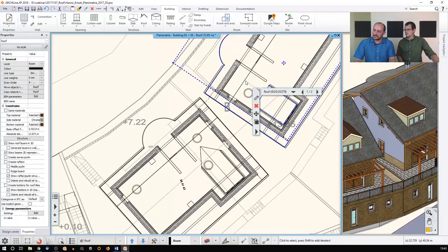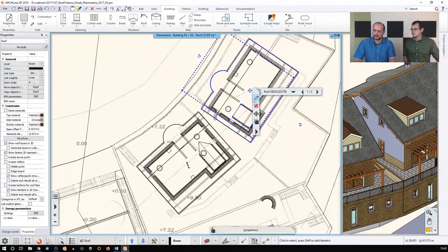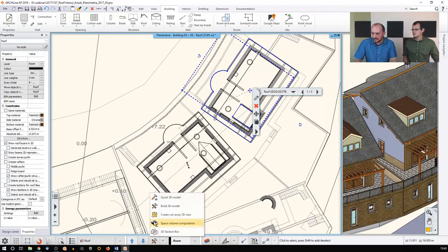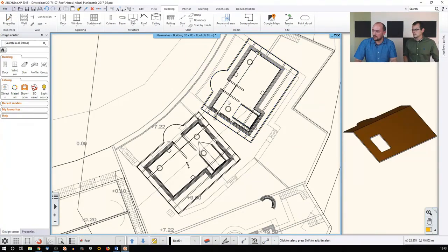So if I select this here, which is the roof itself, let's just make a quick cut like last time, so I can demonstrate what happens under the roof. See, there is a hole under it. So this roof structure, the dormer roof, automatically cuts everything under from the roof structure, so you can actually use it when you intersect it. It's a habitable area. So this is what happens there. So it's actually part of the parametric model. It would be a living, breathing part of it.